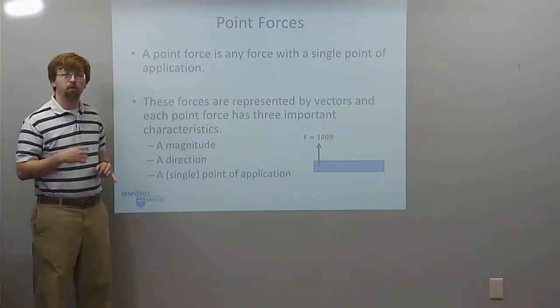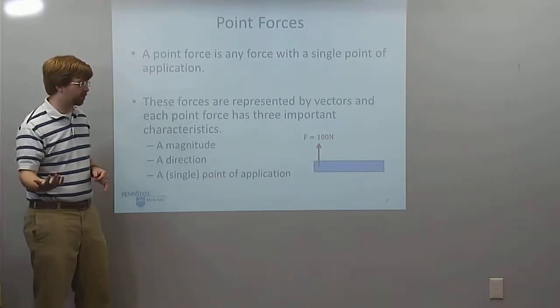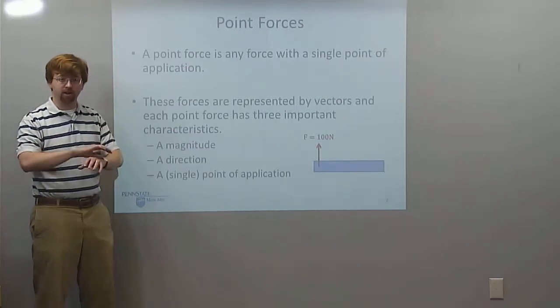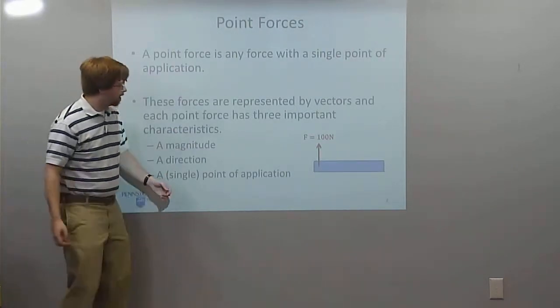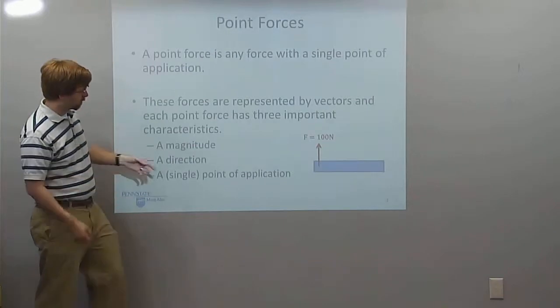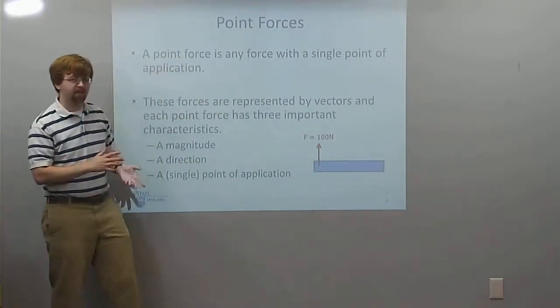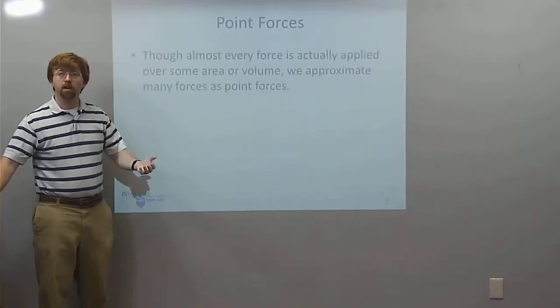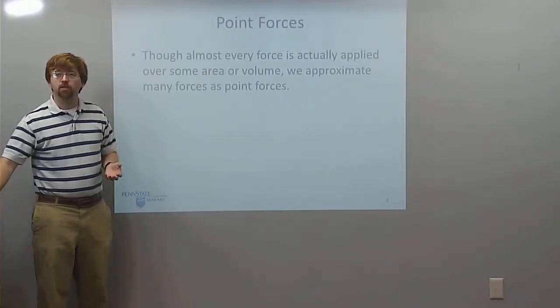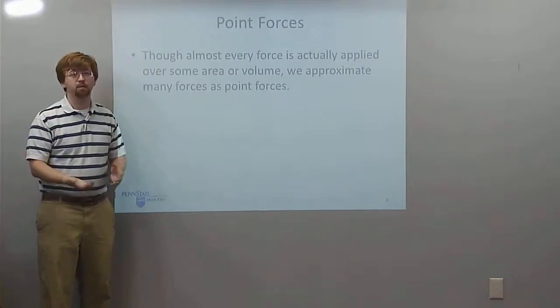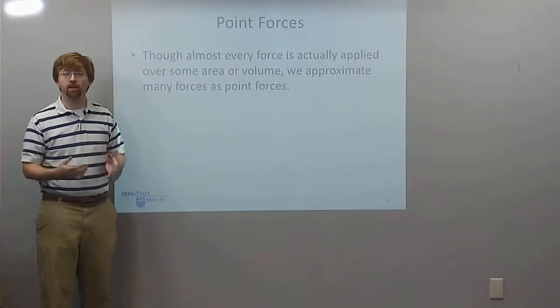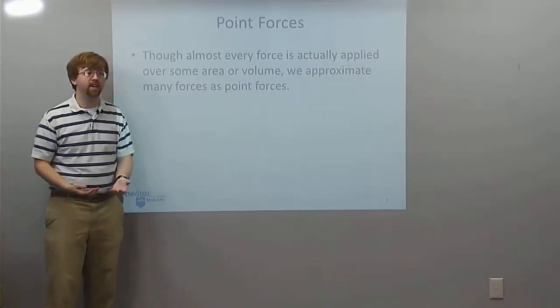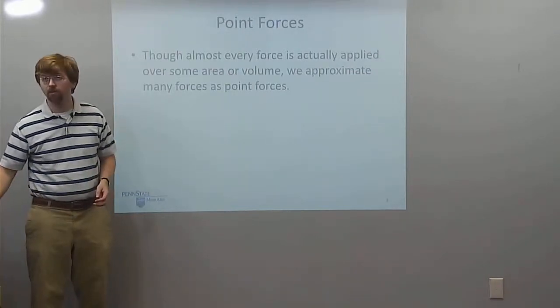This is where point forces differ from distributed forces. Distributed forces are spread over an area. So with our single point of application, we're acting on the left edge of this beam over here. With almost every force, it's actually applied across some area or volume, but we approximate many forces as point forces.